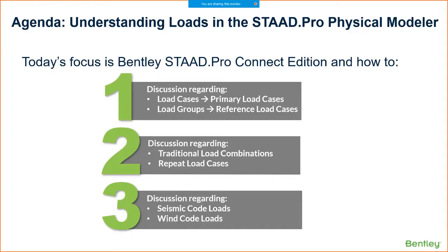We're going to also talk about the traditional load combination options or repeat load cases in the physical modeler and how to control your load combination generation. Now, I did just discuss a detailed breakdown of the different load combination types that we have available in STAAD.Pro in the previous special interest group session.